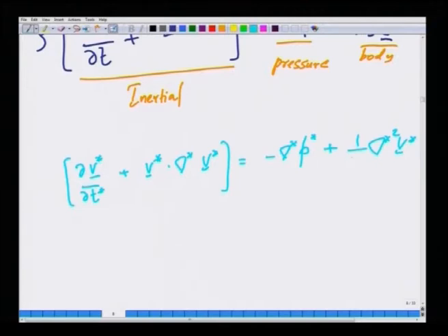I have taken the Reynolds number to this side. So, when the Reynolds number is very large compared to 1, that is, it could be of the order of thousands, then 1 over Re is small. So, the non-dimensional viscous forces that occur in the Navier-Stokes equation are multiplied by a small number. So, we can hope that we can neglect viscous forces altogether to begin with.